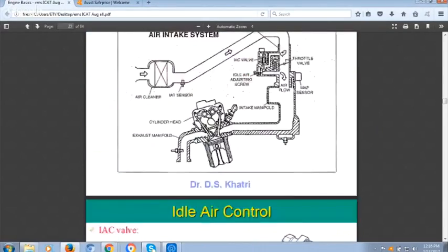And we introduced this for the first time in Maruti, also in India. There are other engines also, Honda and others, that are 4-valve engines. But most motorcycle engines are 2-valve, one intake, one exhaust. Anyway, then we started the designing, because when you have 2 intake valves, you have to connect them through the intake manifold. A lot of computer simulation was done, to see when the flow will be maximum and what type of design I should make. Suppose this is the intake pipe, it is coming from the air cleaner side. If there is a picture, I can just show it.